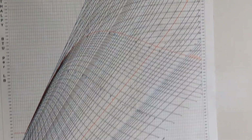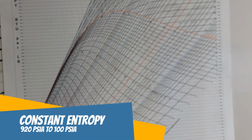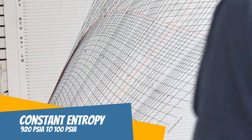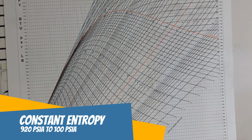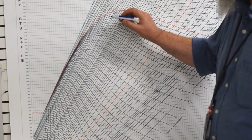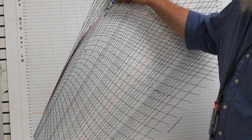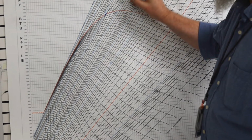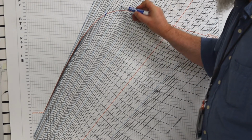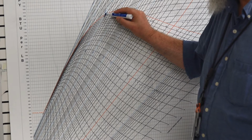For this next one, we're going to go to our Mollier diagram. For this next one, I gave you steam at 920 psia. So first, let's find our 920 psia pressure line on our Mollier diagram. I'm going to be just slightly above the 900 pound line right here. I'm not quite to that blue 1000 psia line, and the pressure lines are running this way, right? 500 pounds down here, 300 pounds, 200 pounds, 100 pounds. So this is the point I'm starting at.